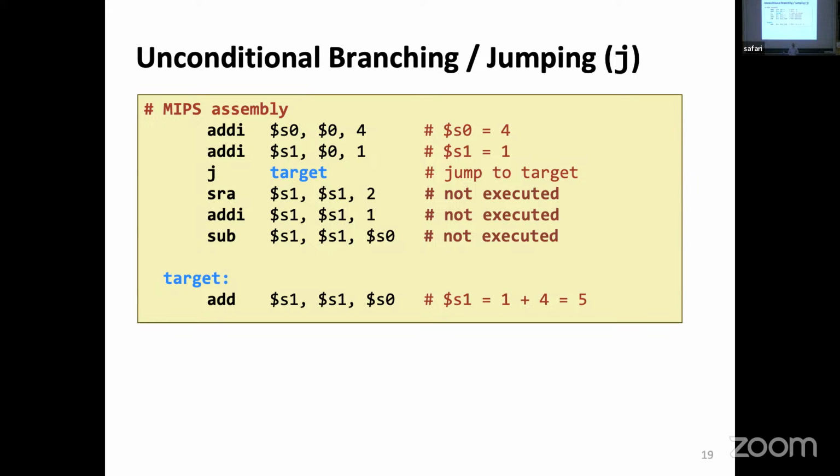We are either going to give it a relative address, meaning normally the next instruction you would have executed is at this address, wherever that is, and we say, instead of going there, go 10 further, go 15 back. That's one version. The other version is, like this one, we exactly tell it where to go. Go to address 008000044, whatever it is. And it says, oh, you know what, I'll just go there. He told me to go there.